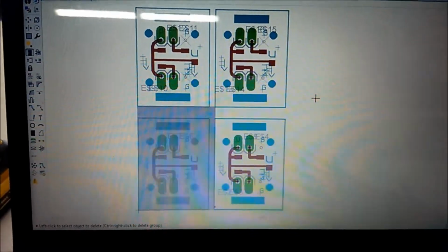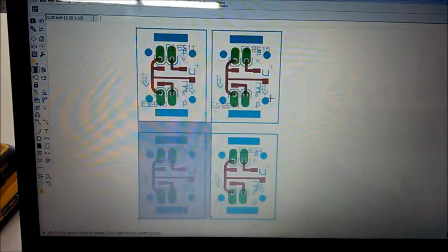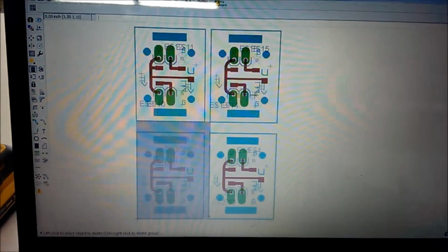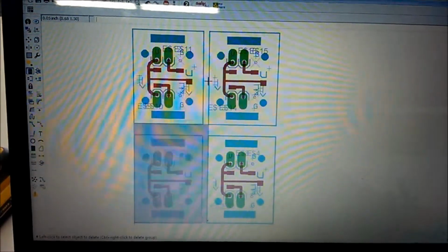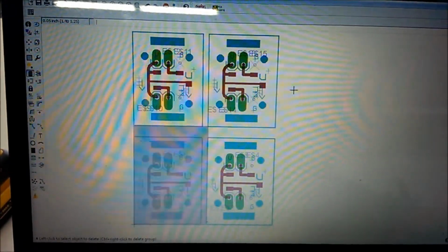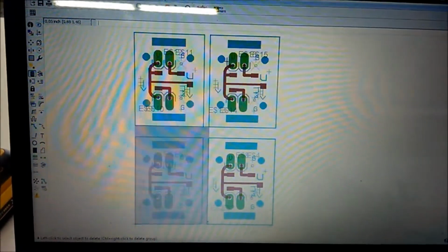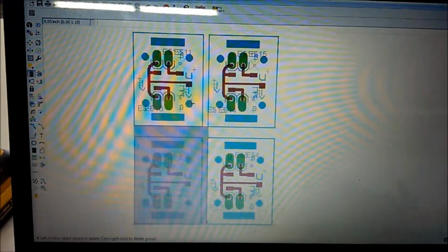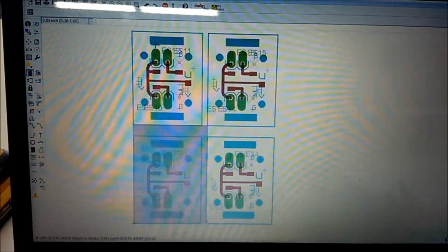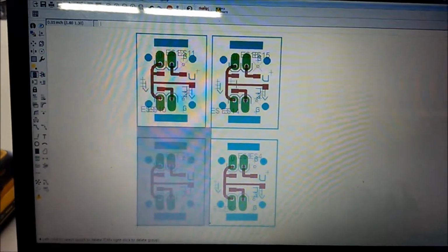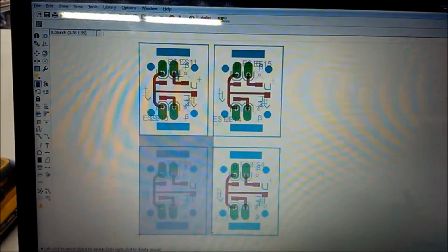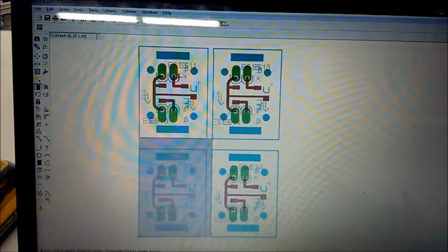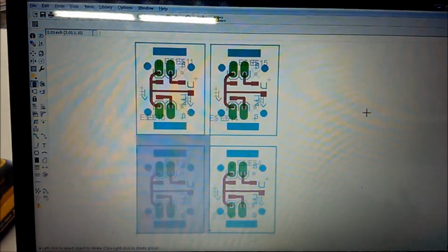Hey everyone, I'm here at the SoDo Makerspace today working on some wearable projects, and this is a carrier board that I designed for the NeoPixels that Adafruit sells. I went ahead and added a couple of little holes here for doing sewing, and then also a slot which I'm going to try out to see if it'll hopefully stabilize the ribbon cable that I've been using for these, so I don't get any solder breaks when things get flexed.